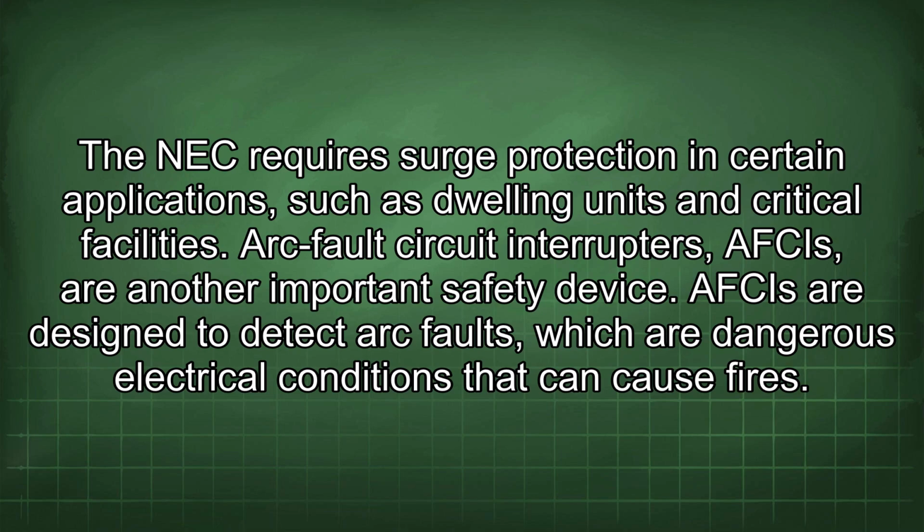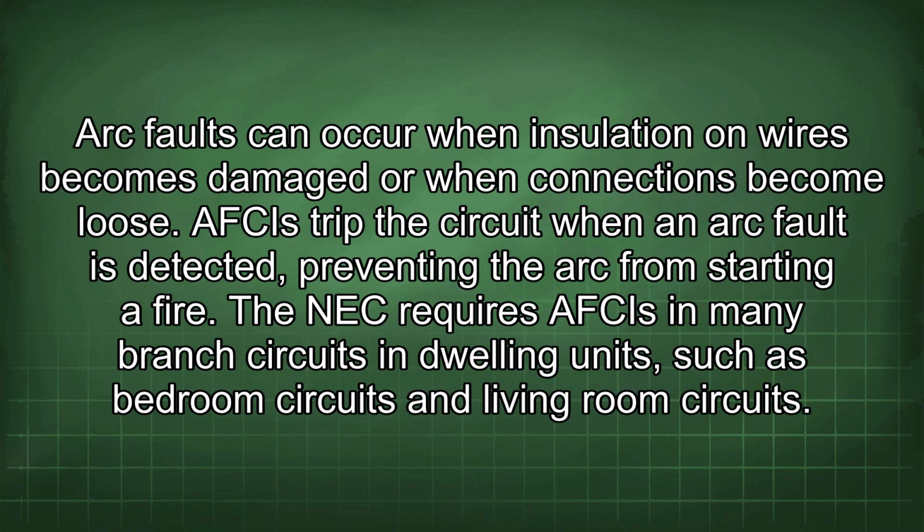Arc fault circuit interrupters, AFCIs, are another important safety device. AFCIs are designed to detect arc faults, which are dangerous electrical conditions that can cause fires. Arc faults can occur when insulation on wires becomes damaged or when connections become loose. AFCIs trip the circuit when an arc fault is detected, preventing the arc from starting a fire. The NEC requires AFCIs in many branch circuits in dwelling units, such as bedroom circuits and living room circuits.